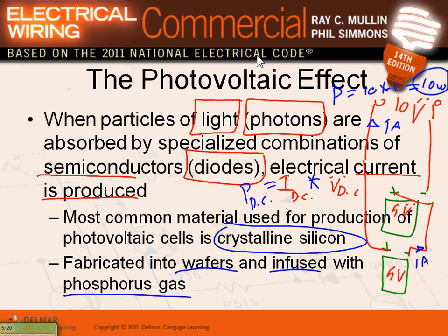They're smarter than that. Take this. They come over here and they put another panel here. Here's 2 panels, right? Plus, minus, plus, minus. They bring the same thing. See how we repeat itself? And we know what they do. They tie the negative to the negative and the positive to the positive.